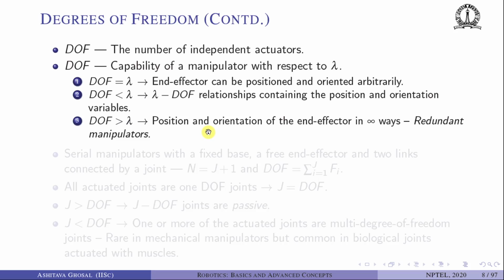We'll see later when we look at parallel mechanisms, for example, the 4-bar, that the coupler, or some point on this mechanism, cannot give any x, y, and phi. There is some relationship between x, y, and phi. How many relationships? Three of them, because degree of freedom is 1 and lambda is 3. Sorry, two of them, two relationships.